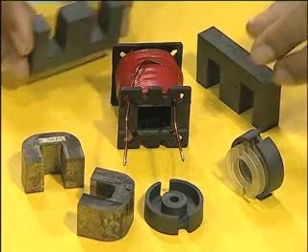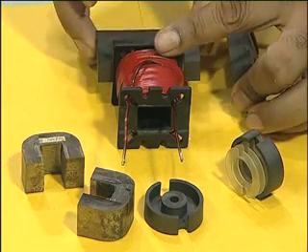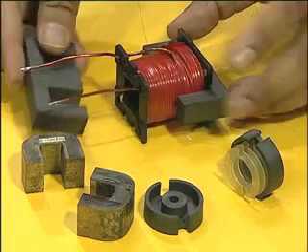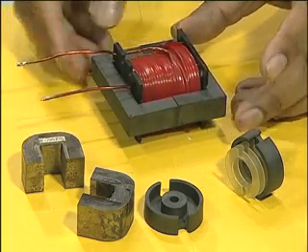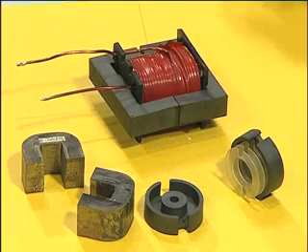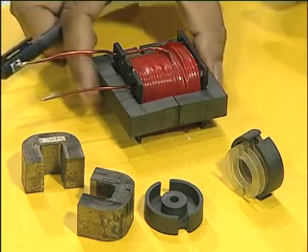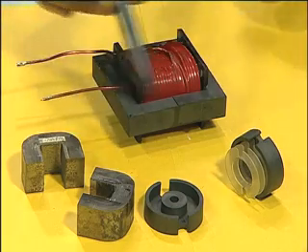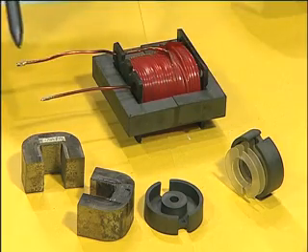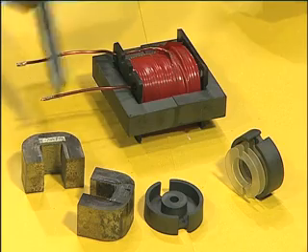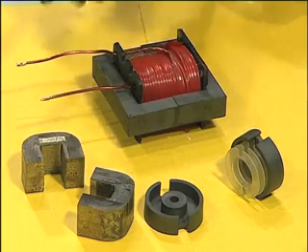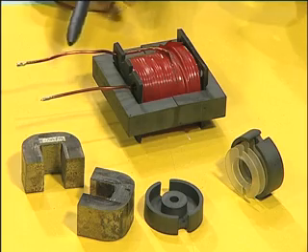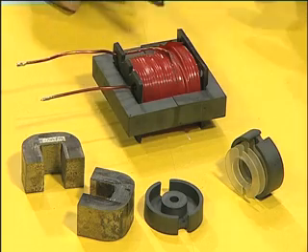And after winding, you take this core, put it like that, and assemble it in this manner. So, this becomes an inductor with a ferrite core. So, this is a ferrite core. Okay. You have one end of the winding here, another end of the winding here, goes through this coil, there is a bobbin, this bobbin is fitted into the core, is a ferrite core, ferrite EE core.